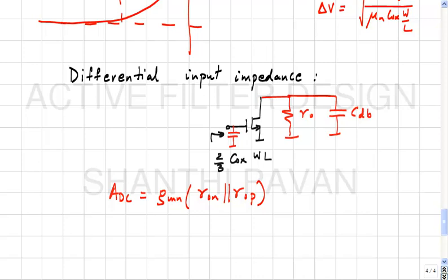But at least it's a capacitor, and you can account for it in the integrating capacitors, right? Now, if you keep taking every capacitor and accounting it for the integrating capacitor, then what if you have no integrating capacitor left? That means the frequency at which you're designing is so high that you can no longer do it in this technology. You've got to go to a better CMOS technology where the parasitics are lower. That's all it means. If you have a given technology, there's only so much you can do. Okay. All right.